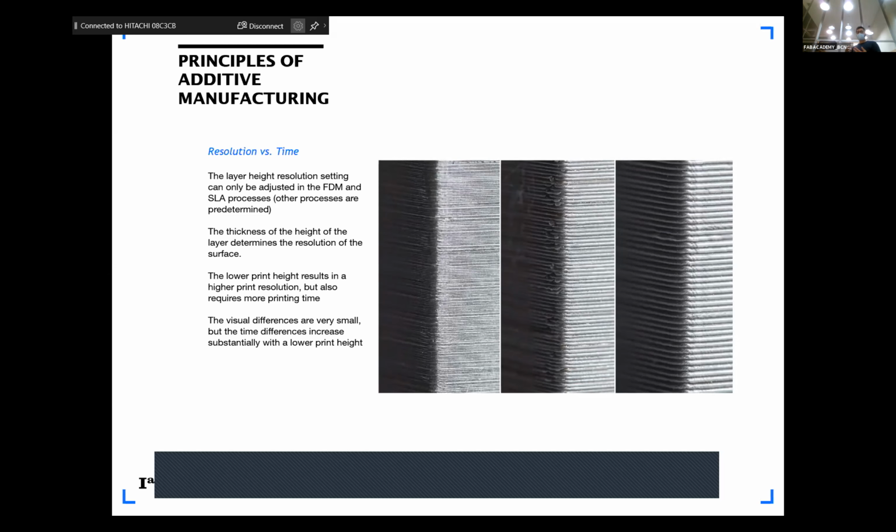So we have the same principles, and we work by making 2D layers. And clay extrusion usually needs to be done way slower, because the material doesn't cool down, it's always fluffy. You need to print slower so it doesn't move, because if you print paste really fast, you basically drag the material. Imagine trying to print jelly. It's actually the same. What you can print, as I say, is anything with a toothpaste consistency.